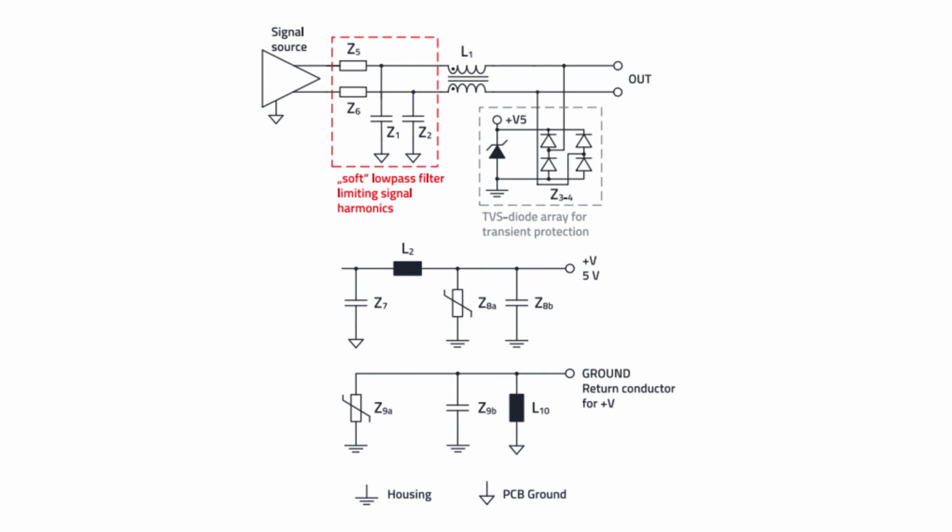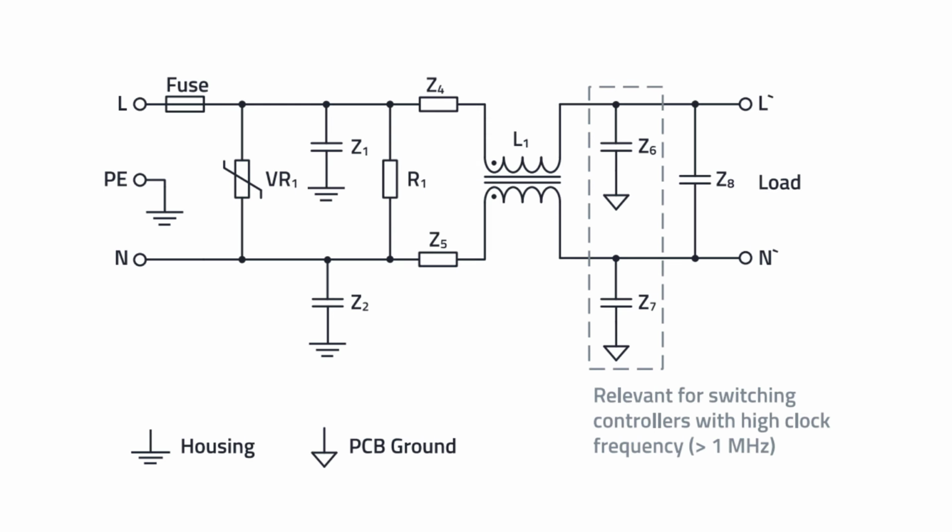Ensure that the current carrying components are compatible with the required minimum rated current. We should also consider a power line filter with transient protection, and a power line filter of protection class 1 with a protective conductor. We can see this in our diagram attached. It contains all the components that are necessary for the filter circuit.